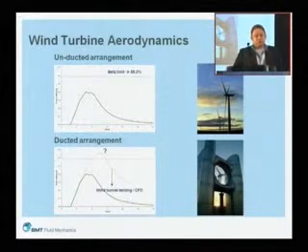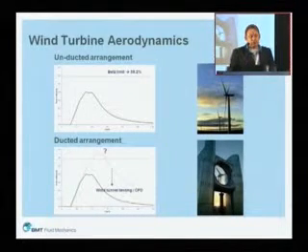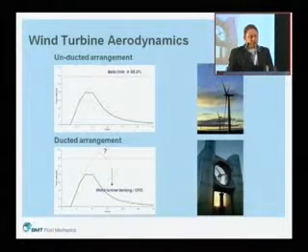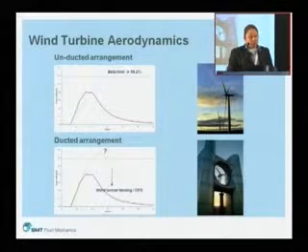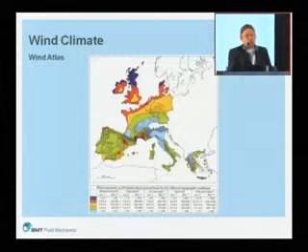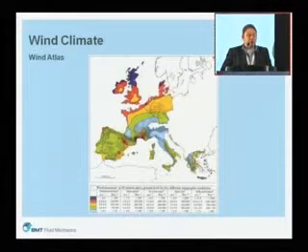But it's important to note that if you are involved in a commercial project that requires this sort of technology, there are no commercially available ducted wind turbines out there, and all of the performance data that you have for off-the-shelf machines apply to an unducted configuration only. So some research needs to be done into what the aerodynamic performance of large-scale ducted turbines is. At the moment, it's somewhat of an unknown.